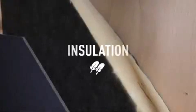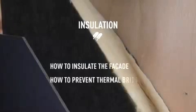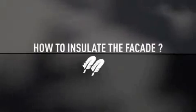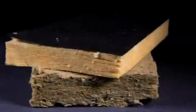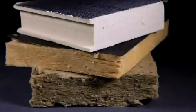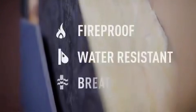Insulation. In this section, we will look at how to insulate the facade and prevent thermal bridges. How to insulate the facade. The insulation, be it a mineral wool or a foam-based material, must be thick enough to suit the building's function. Each product has its own characteristics and level of performance. Ideally, the insulation should be fireproof, water-resistant, and breathable.